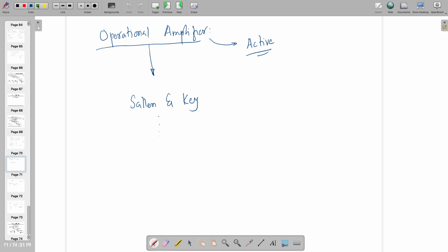If it is a circuit which is LC, you need to look at the properties of LC, which say that all the poles and zeros have to be in the left half plane. The roots will be simple, meaning they will be on the j omega axis. There is no real part.